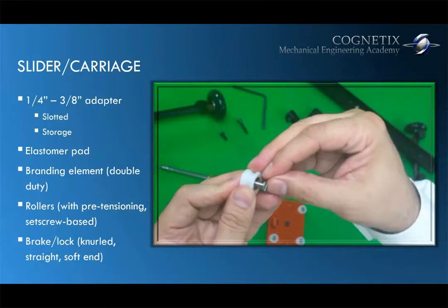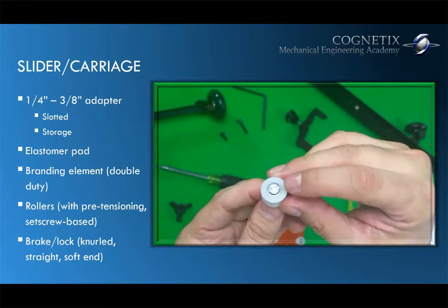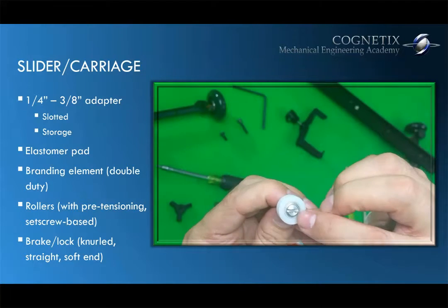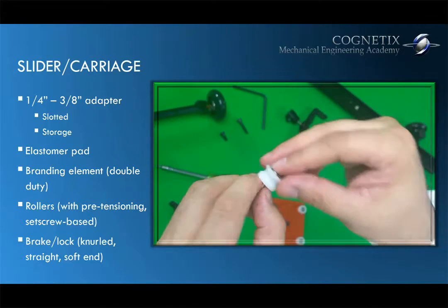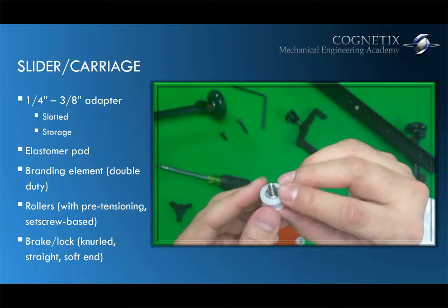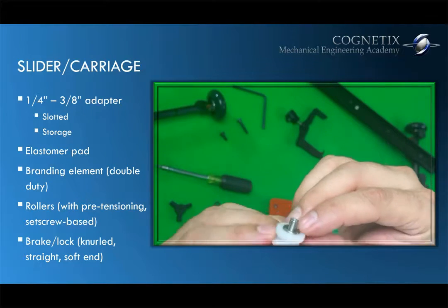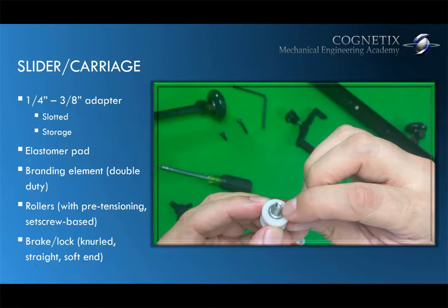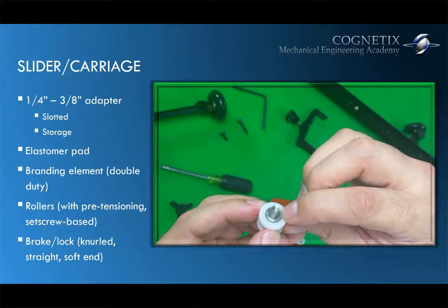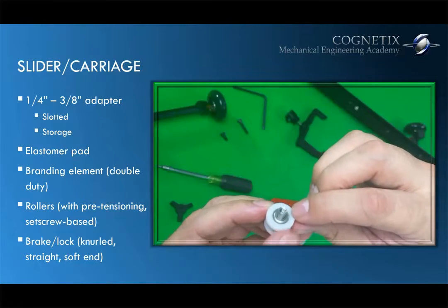Put it back in. So it's designed to only hold the inner race. It keeps the inner race from spinning. Okay, on the other end, knowing that, we need a component that will contact the inner race, but not the outer race, so that it spins properly.